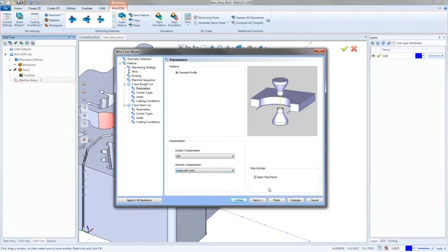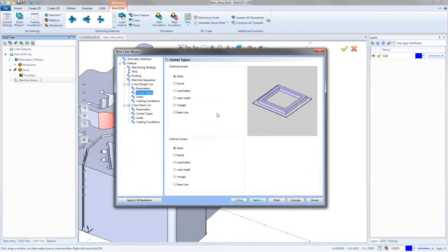Right down here are your stop settings. So if you have a stop point along here where you need it to stop so you can glue up, you can apply stop points and actually tell it when to stop. I don't have any stop points, so it doesn't really matter. The corner types are primarily used for getting rid of excess, cutting a little bit more in the corners, maybe so a part can drop out, giving a little relief on those cuts. So you can leave it on sharp, or you could say, I want to round it.